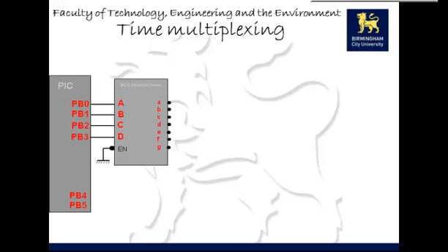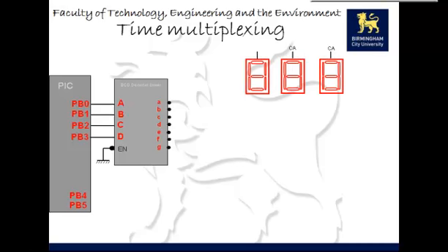The device also has active low outputs, which means that you've got inverted outputs. On the output of the decoder driver, you can just imagine there are some NOT gates there which invert the output. So it's the opposite to what you would think it should be. Now we've also got 4 7-segment displays. In more detail, we've got 4 common anode 7-segment displays, and because they are common anode, connecting these to the outputs of the decoder driver will make it work as if it was not inverted outputs.